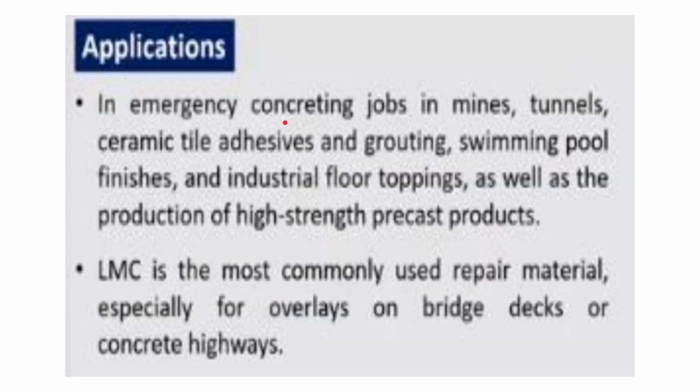Let us see what its applications are. It is mainly used in emergency concreting jobs in mines, tunnels, ceramic tile adhesives, and grouting, swimming pool finishes, and industrial floor toppings, as well as the production of high strength precast products. So these are mainly the applications of LMC, latex modified concrete.